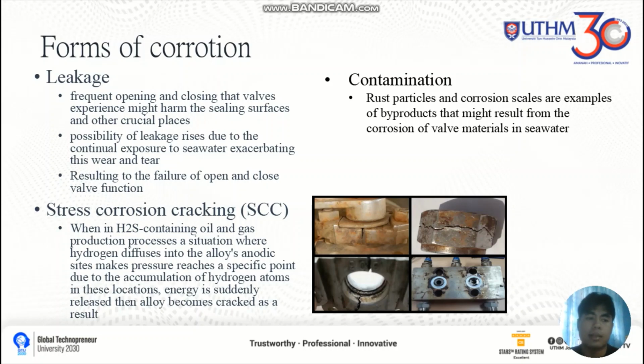The second is stress corrosion cracking, SCC. In an H2S-containing oil and gas production process, hydrogen diffuses into the alloy's anodic sites, making pressure reach a specific point due to the accumulation of hydrogen atoms in this location. Energy is suddenly released, then the alloy becomes cracked as a result of this reaction.